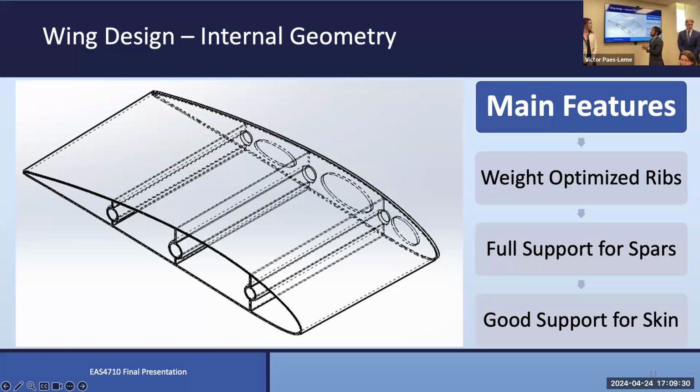Going back to Mr. Singer's comments about aerospace structures, the margin of safety of 6 goes back to that. For that loading condition, a good amount of it is constrained by the fact that we had to increase the geometry because we were using lightweight PLA. We tried going with one single layer, and also there's the size of the wing itself. So I think this one we could definitely just get rid of and make that a regular spar.